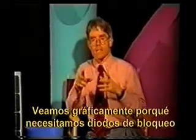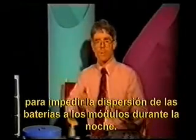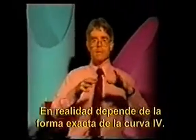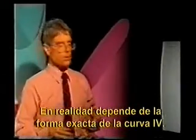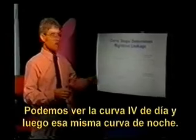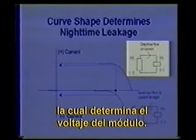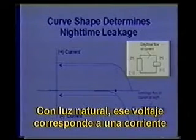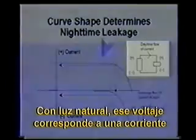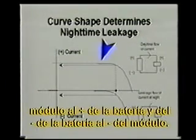Let's take a look graphically at why we might need blocking diodes to prevent leakage from our batteries through our modules at night. It really depends on the exact curve shape of our IV curve. We can look at an IV curve during the day and then that same curve at night. During the day, we have our module connected up to a battery. The battery determines the module voltage. Under daylight conditions, that voltage corresponds to a positive current. In other words, we have current flowing from the plus of the module into the plus of the battery, and from the minus of the battery into the minus of the module.